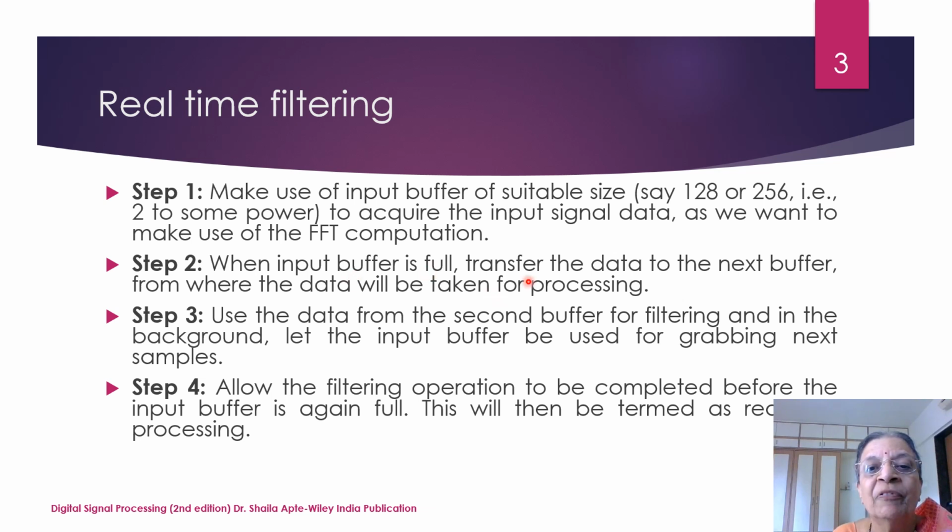So when the input buffer is full, transfer the data to the next buffer from where the data will be taken for processing. Now use the data from the second buffer for filtering, and in the meantime, let the input buffer be used for grabbing the next samples. The filtering operation must be completed before the input buffer is full again. That is a requirement because unless the operation is completed, we cannot transfer the data again from the input buffer to the output buffer. So this will be termed as real-time filtering, real-time processing.